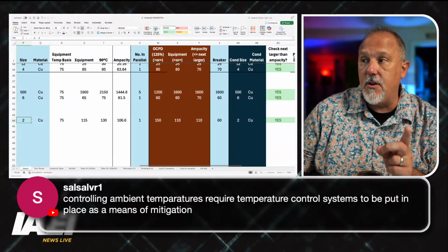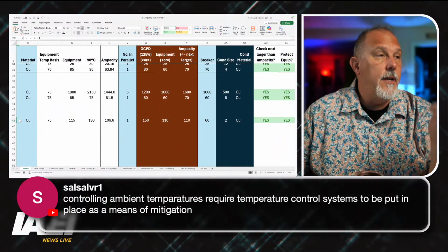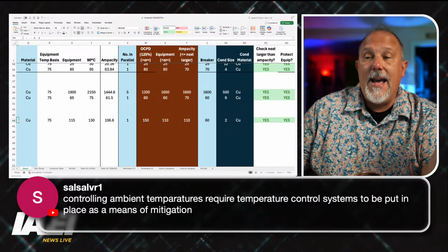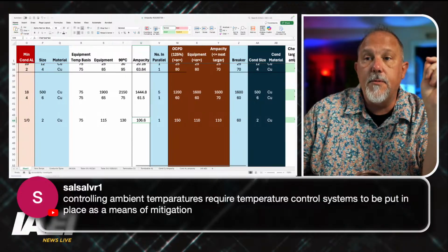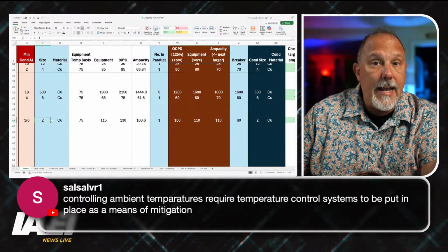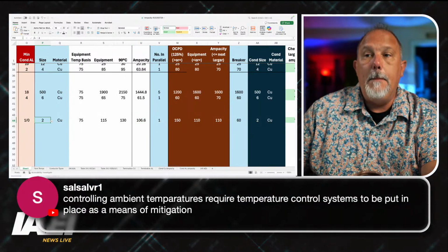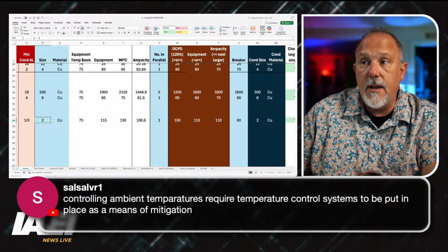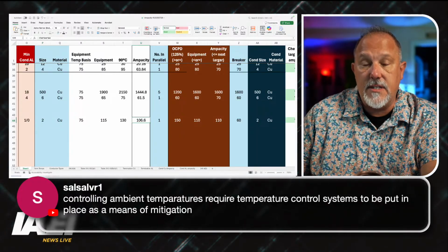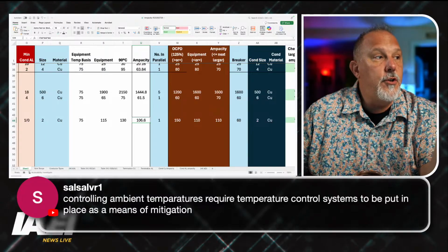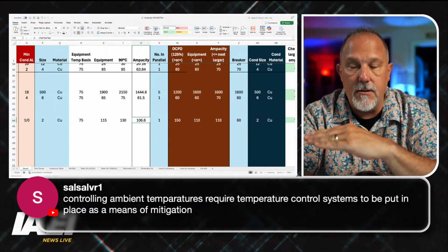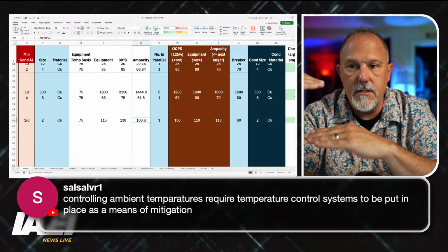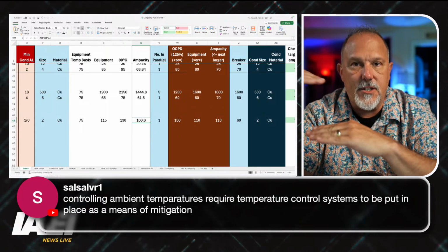And then I pick my overcurrent protective device, which, now, if my ampacity is 106.6 amps for a number 2, for a 2 gauge conductor, based upon those conditions of use, my ampacity is 106.6. 240.4(B) tells me I can go to the next higher overcurrent device on that circuit.